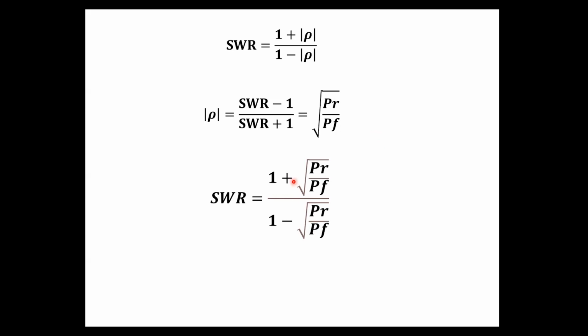All right, so I can actually calculate, if I can measure my reflected power and my forward power, then with this little formula right here, I can calculate my SWR. And I can tell you back in the 70s when I was in the Air Force, that's how we did it. We got our little power meter and the little slug in it, and you pointed the slug one way and read the power, and you turned the slug back the other direction and read the power, and then we just had a little nomograph on there that did this calculation for us by an analog method. And later on, when I got a snazzy calculator that I could program, I could put the reflected and the forward power in it and got my SWR. Kind of neat and spiffy.